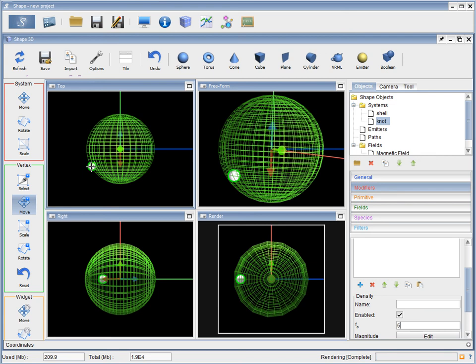If you don't want to use the selection of the vertices, then you can use other geometry modifiers that also transform only the vertices and move your object without moving the local coordinate system. Such a modifier could, for example, be the shear modifier that you set in such a way that it only moves the object in some direction.